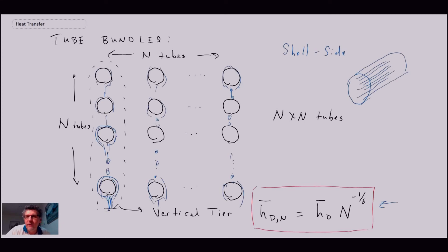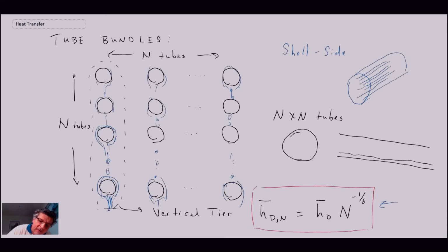Now, if it was tube side condensation, then we would be looking at a condensing unit where we have the condensation occurring on the inside of the tubes, and sometimes there'll be a little slope and the liquid will build up. If you're to look at the cross section of this, what's happening is you get the film building up on the inside, it runs down the walls, and then you get a layer of liquid forming on the bottom. And so your film then is on the inside. That would be tube side condensation, and this is shell side condensation.